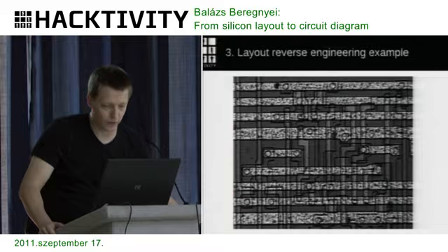So first I will look for the transistors with double width, so we know that this aluminium wire is the power. We also see here loading transistors, so this is also power. We also have aluminium wires that are not connected at all, so they are just passing by.